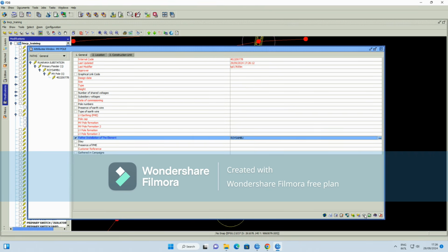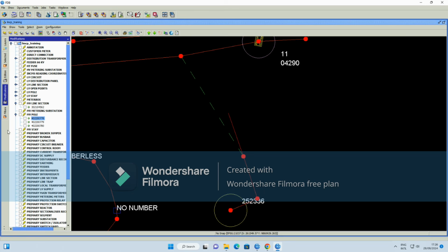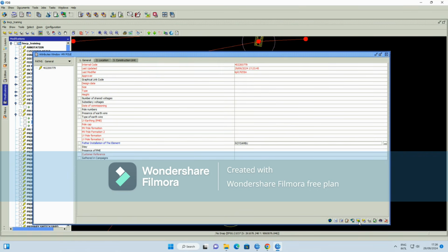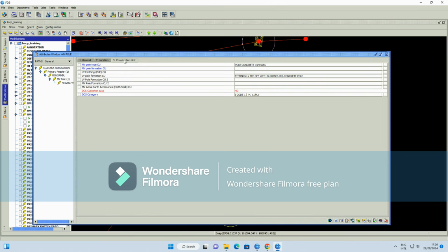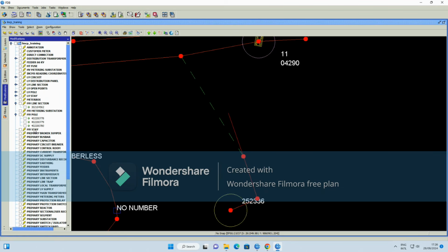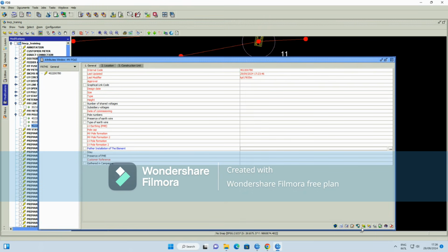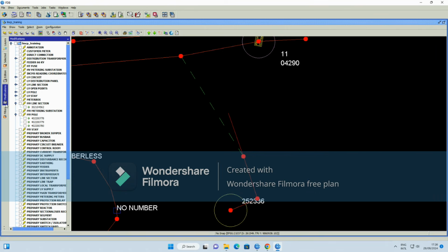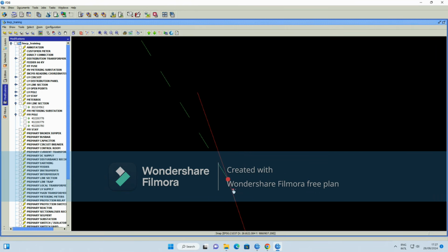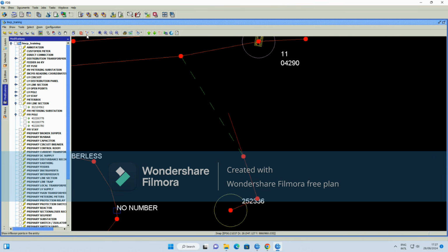This is one of the ways you can edit. Save the template, open the other poles, and fill the template and save. That is one way of editing this data, especially when you're not working with a lot of poles. But if you're working with a lot of poles, maybe a whole scheme, you may need to do multiple edition. And there, our poles are okay.